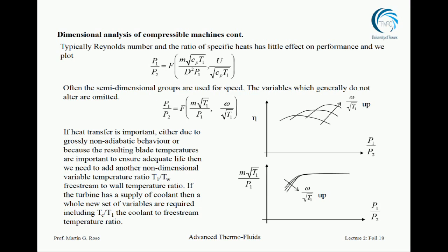Well, the big thing with an aeroplane is you want it to be as light as possible. And so if you added onto it a mechanical drive, driving wheels making it go backwards, it would add weight and cost to the aircraft, and you have to carry it for 10 hours at a time around the world. So that's why it's better to put a little tractor on the ground to push the aeroplane, because you don't have to take it with you. You can leave it on the ground. It would probably be 10 tons, such a vehicle, and you don't want to carry 10 tons you don't need. So that's why you don't enable the plane to drive itself backwards.